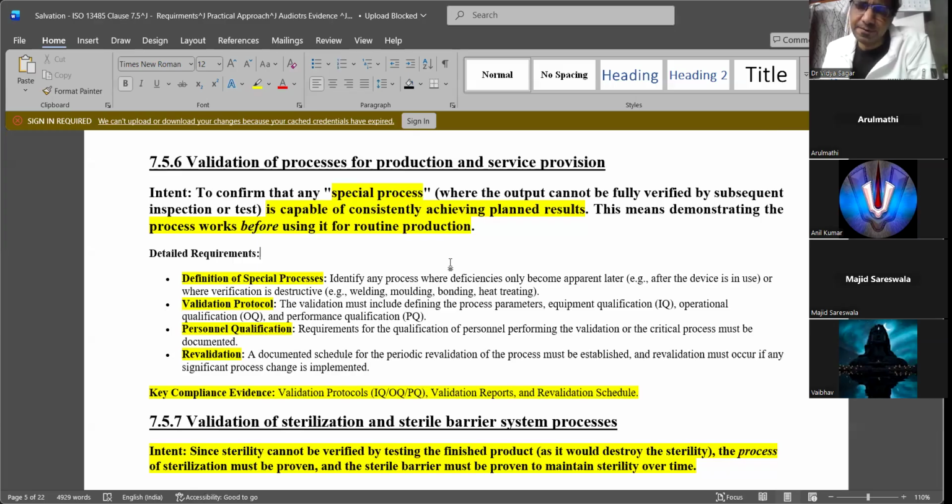There could be very few rejections. Your process is so capable. What we call CPK or PPK, we can check by some equation, what we call process capability and process capacity. There is a separate section for us to discuss process capability, statistical analysis, Six Sigma. Unless you talk about CPK and Six Sigma, you are not really talking anything about your process. You are just a layman extruding something or manufacturing something.